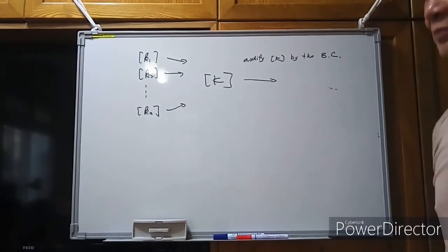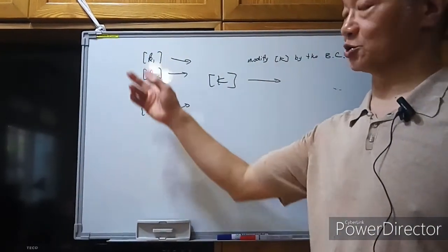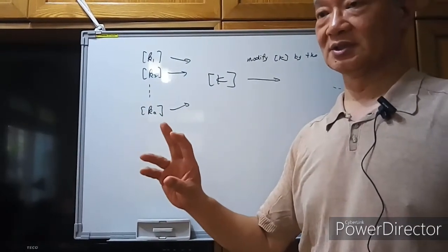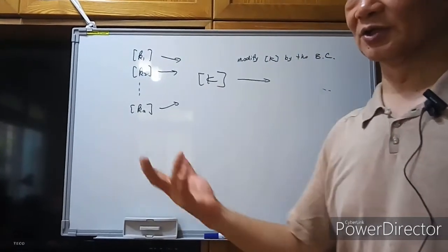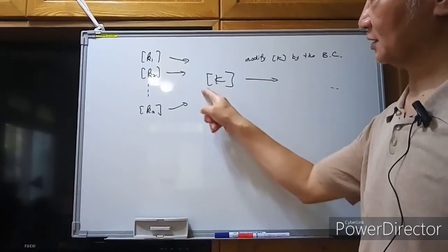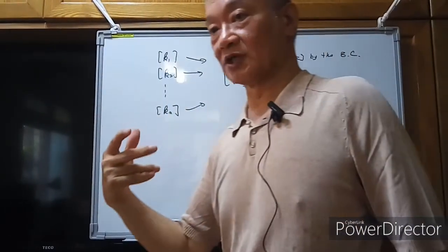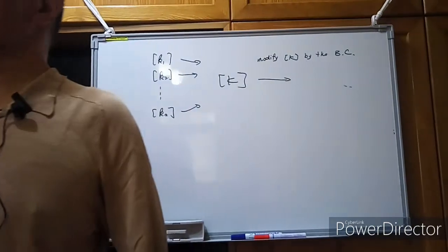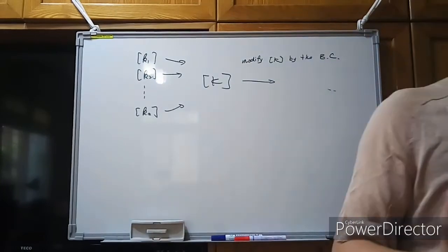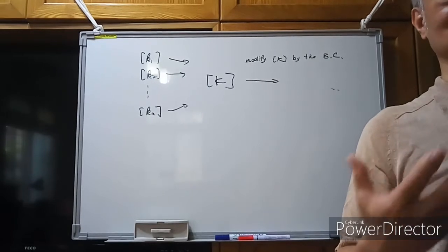So most of the time when we consider the element stiffness matrix, we will assume all the related nodal points have unknown displacements, but we know the force. So that's the assumption when we get the assembled global K matrix. But we still need to consider the boundary conditions, since it is not possible for a structure without any support. If a structure is without any support, then it is an unstable structure.